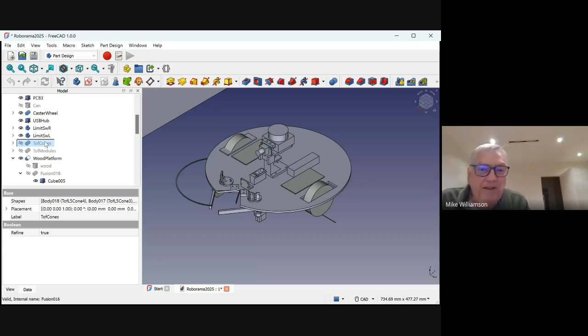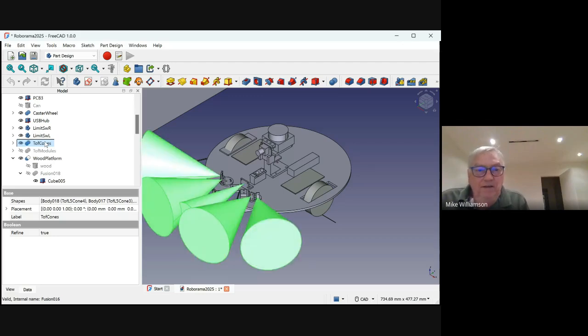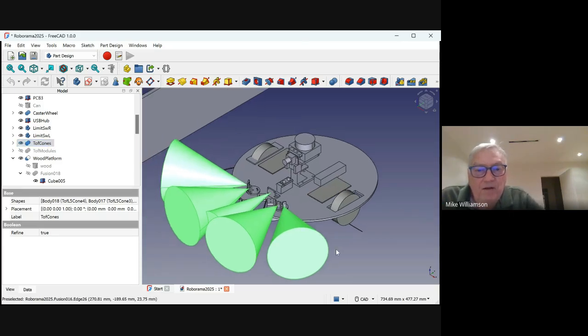It's not going to jam up or anything. And this is the interesting thing here. This is my sensors, the time of flight sensors. You can see that I have 4 obstacle detection sensors that'll basically be able to see 160 degrees or something. And these are the 8x8 sensors, so I'll have a really good range, a field of view. And I can add it to the navigation system to use it for obstacle detection.